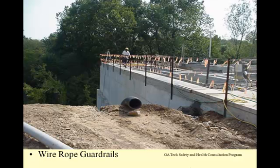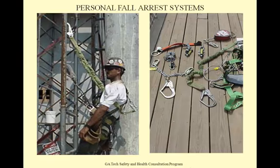If a safety net system is used, it must be installed as close as practicable below the working surface, and the net and its components should be inspected at least weekly. Personal fall arrest systems are comprised of components and equipment that are worn by employees. The lanyards, vertical lifelines, D-rings, and snap hooks must have a minimum breaking strength of 5,000 pounds.